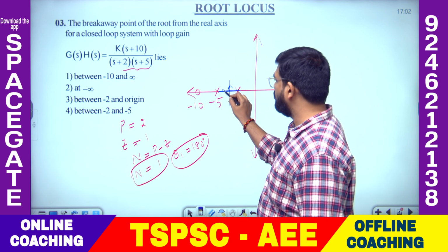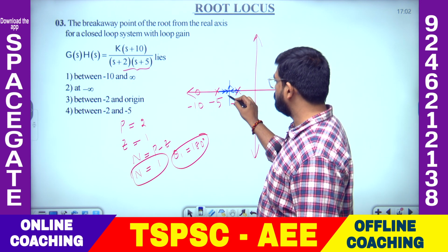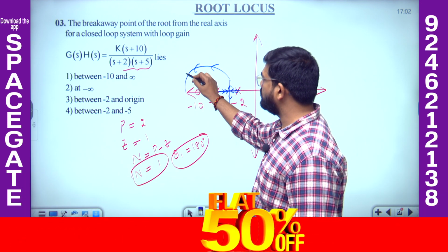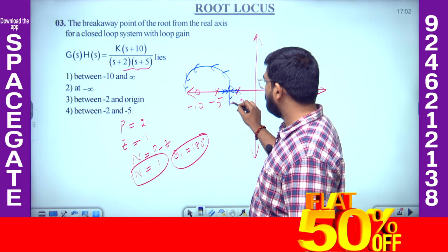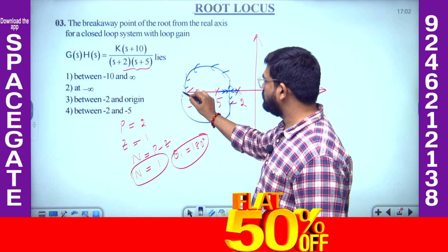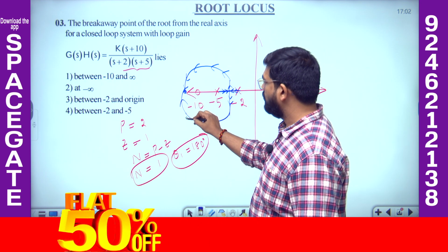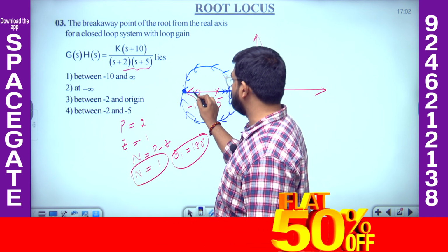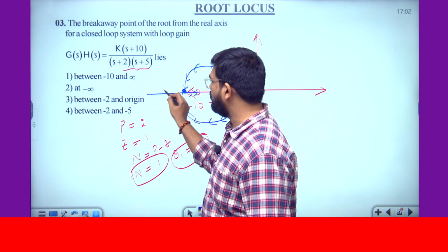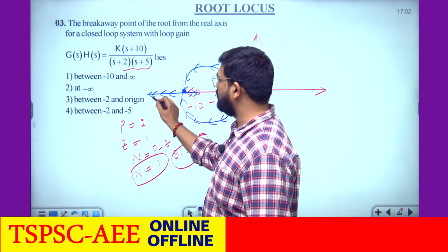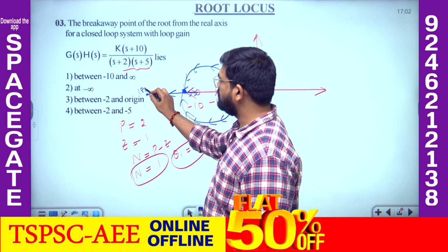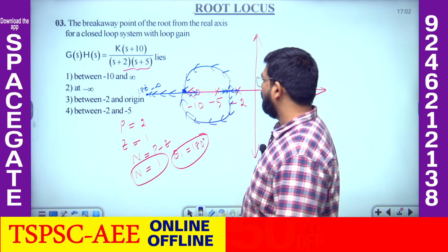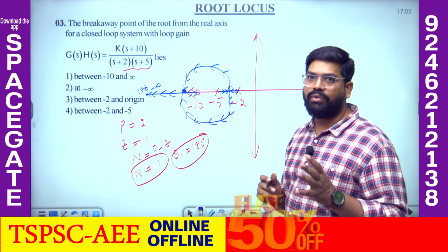Got the point? So root locus, the branch directions I am also indicating. So definitely we will get something like this somewhere. So the root locus branch, right? And here the breakaway point, right? So what will happen? One branch terminates at this 0, and another branch terminates along 180 degrees, searching for 0. So this blue color one indicates our root locus.